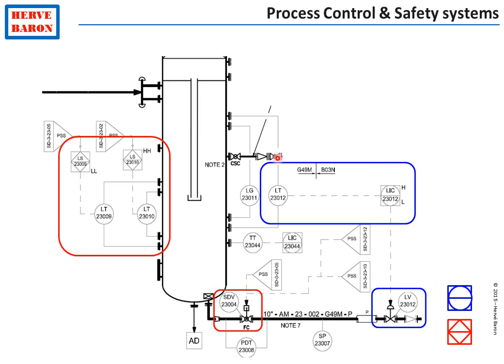As you see, the process control system instruments, shown here in blue, and the process shutdown system instruments, shown in red, are different instruments. Each system has its own instruments as well as controllers. This is so that the process shutdown system is a protection in case of failure of the process control system. They don't share any instruments, so the process shutdown system acts as a backup for the failure of the process control system.